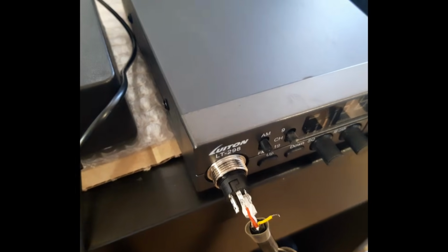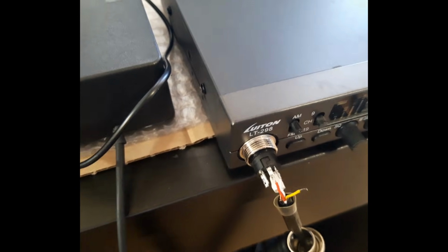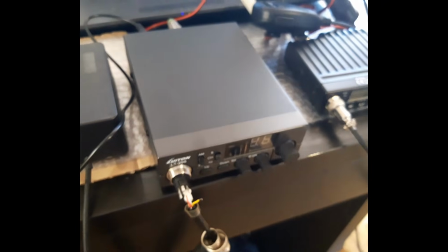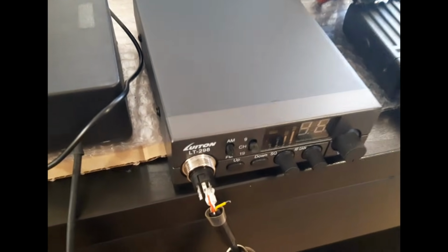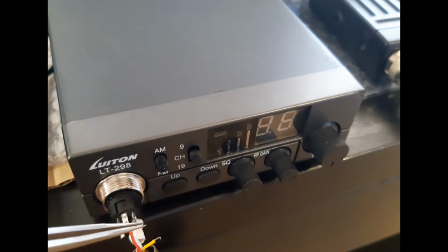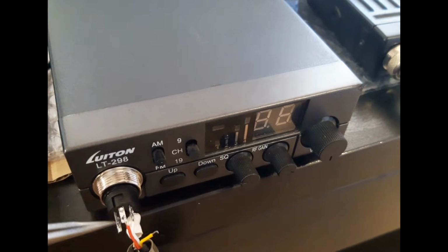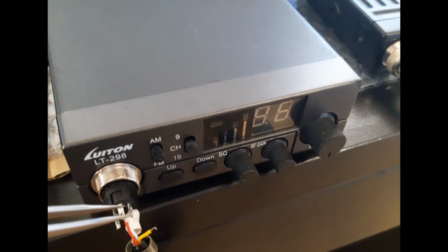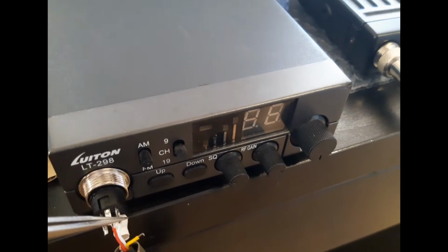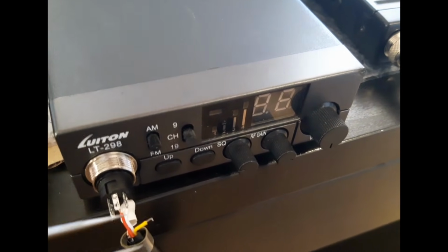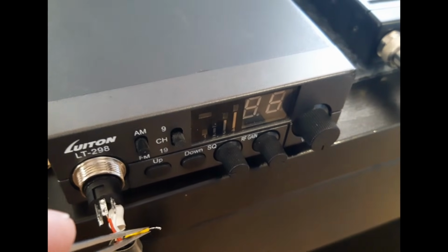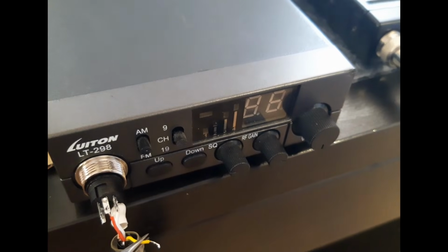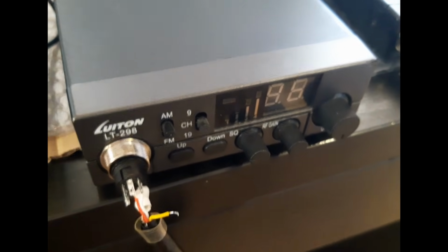And what is this strange disconnected wire we can see here? Since this radio gateway is intended for professionals and radio enthusiasts, many users will immediately understand why it has been done. The standard interface cable includes ground or shield, the PTT transmit control line, the microphone audio line that sends sound to the radio, and an additional audio signal from the radio speaker. This last signal is required for the so-called polite mode, which prevents Ruspo Relay from transmitting periodic announcements while the CB radio channel is already busy.